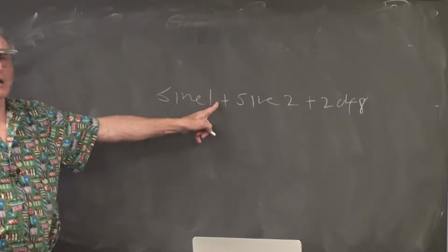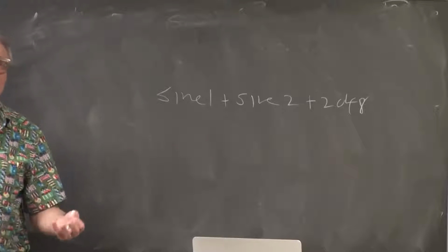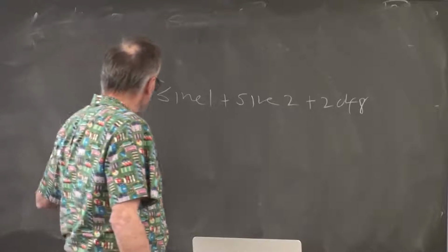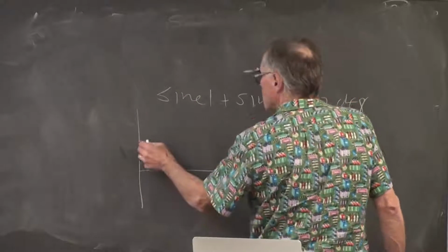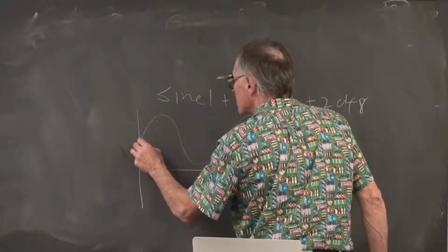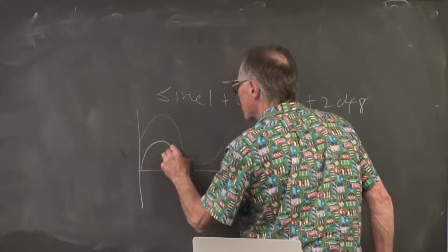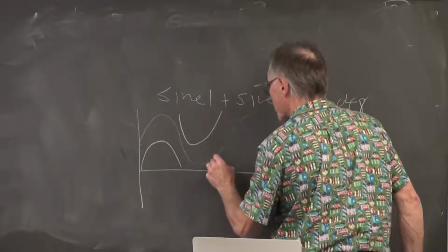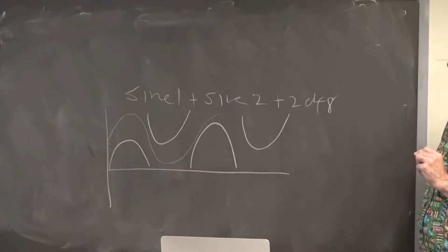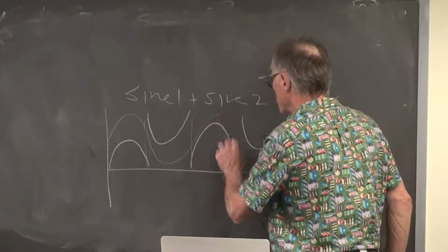And if that number ever overflows, you get a very characteristic waveform that's easy to recognize. It's going to look something like this. You expect to see something that looks like this, and what you're going to see is, it's so messed up I can barely draw it, something that looks like this. You're going to see chunks that are disconnected with a very fast transition between them.